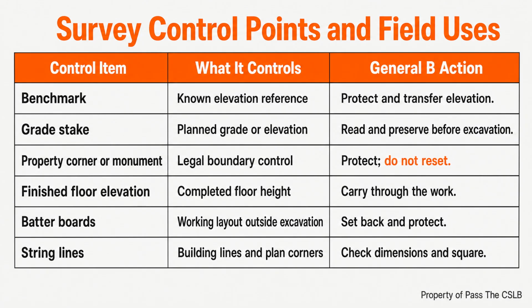Finished floor elevation controls the intended height of the completed floor. Batter boards and string lines preserve working layout outside the excavation area. The chart is not a substitute for the plans or the survey. It is a reminder that each item answers a different question.